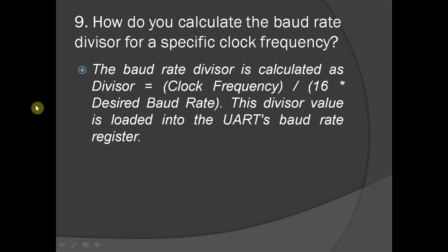So if the transmitter frequency is high, then the data from the transmitter is passing fast now. Then the receiver can't keep up. That's why we are using asynchronous FIFO. If the transmitter is sending the data slowly and the receiver is receiving fast, then there is no problem in that case.